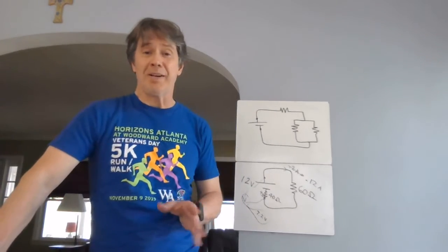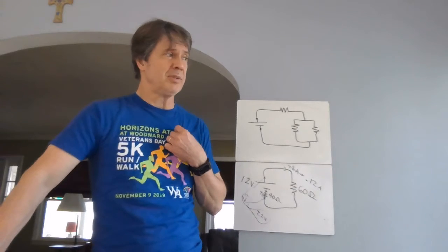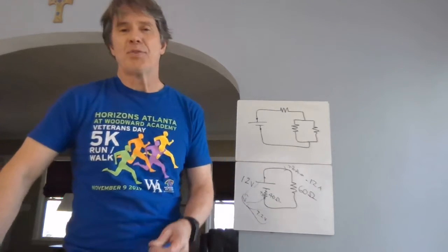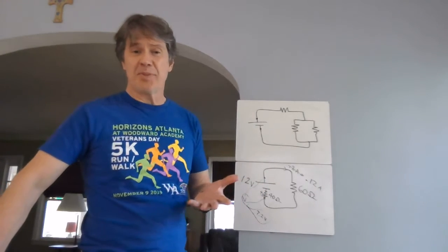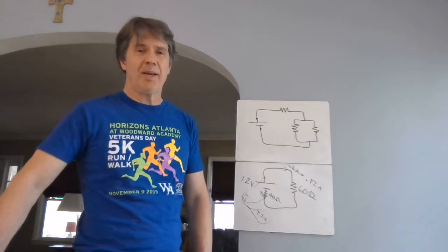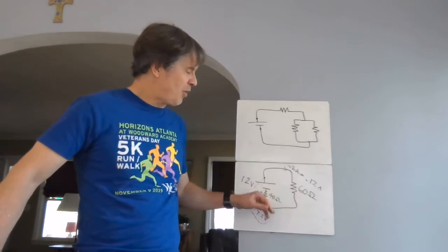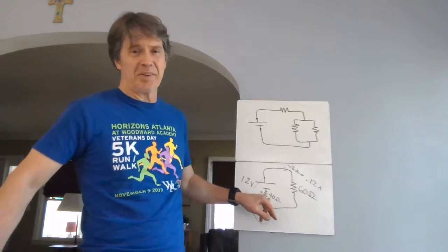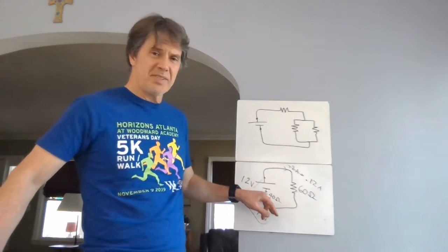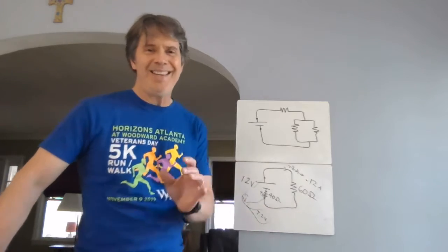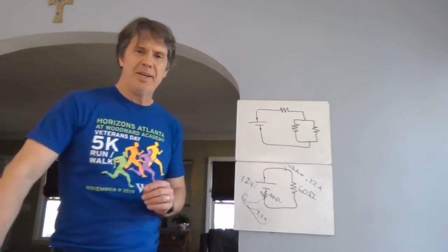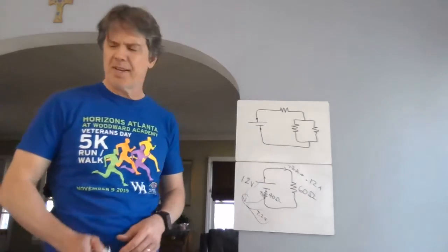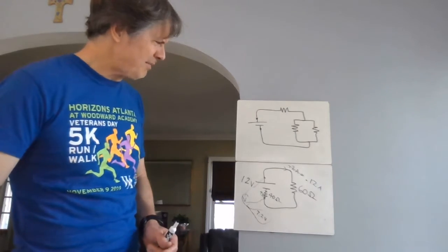Well, I've actually done this with car batteries. This has actually been an issue sometimes. I remember multiple times I couldn't start my car. I didn't know if it was the battery or the starter. So I would put a voltmeter across the battery. It's supposed to be 12 volts, and it'd be close to it. But when you try to start it, the voltage drops because current tries to flow. If there's a big internal resistance, the voltage will plummet as you start to use it. The EMF of the battery is still 12 volts, but the terminal voltage across it is less because some of it is getting eaten up by internal resistance. I guess maybe I've made my point with that for the moment.